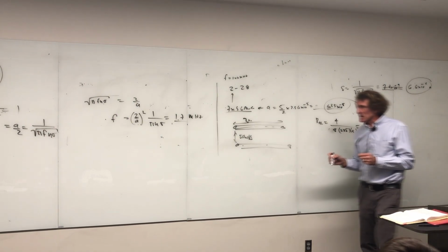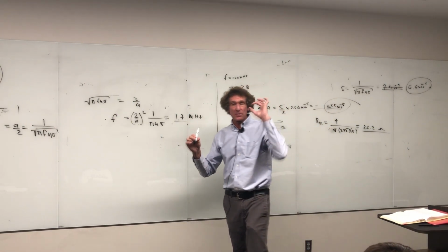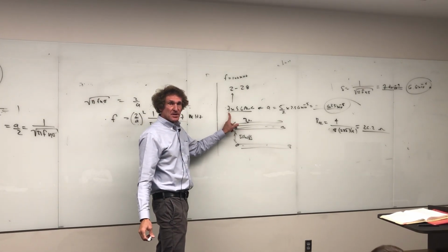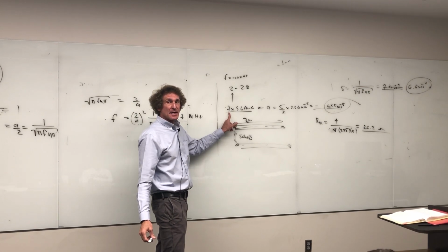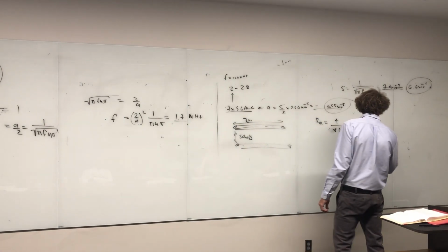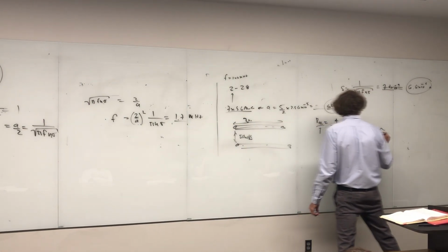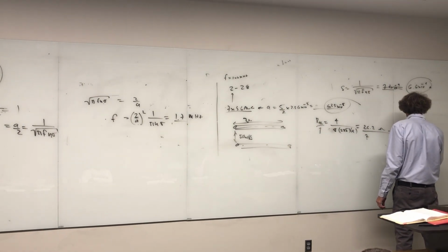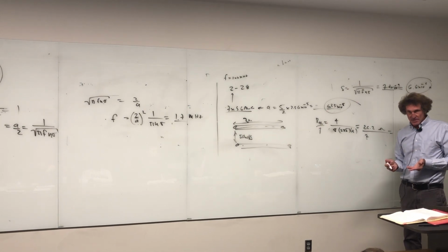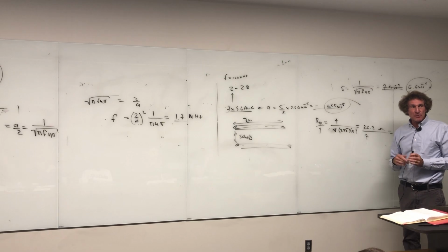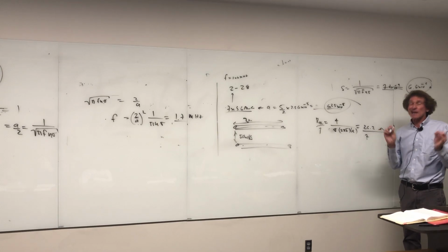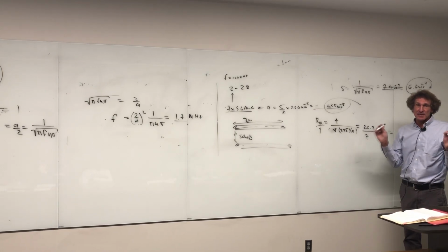Now, the next thing you do is take a look at how many are bundled in just one bundle of wires. And the number that I was given, there's 7 of them, right? You all see this? First number's the number of wires. Got it? So you divide that by 7 to get the actual resistance. If you divide this by 7, 3.74. Is that what it is? 3.74 ohms. Now that's going to be the resistance of the wire. Is that what the answer is? Y'all understand it's not hard to do this, but you've got to be straight in your head because you can make small errors and you get lots of points taken off. Here, exactness pays.